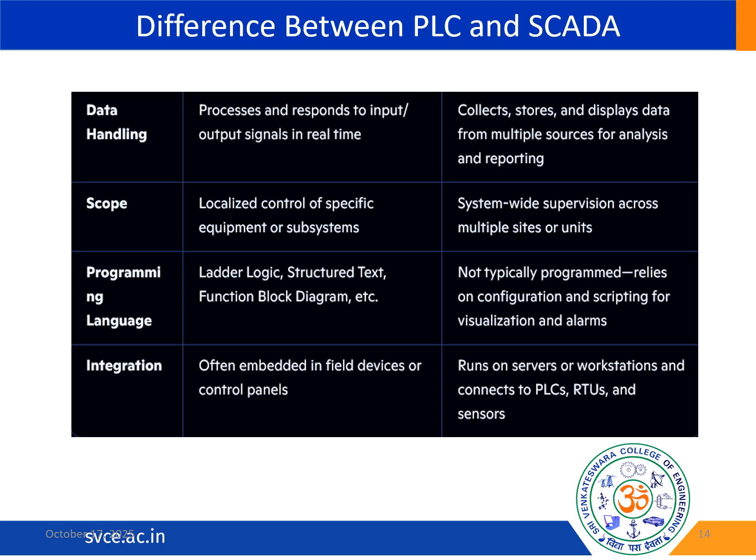It considers some output variation to control these field devices. For example, we can stop the motor. SCADA systems sit on top of programmable logic controllers. PLCs are always part of a SCADA network, and they form an interface between the field and SCADA.